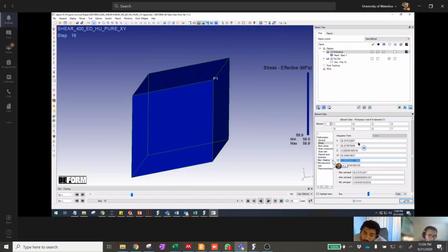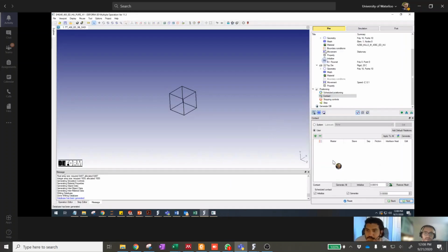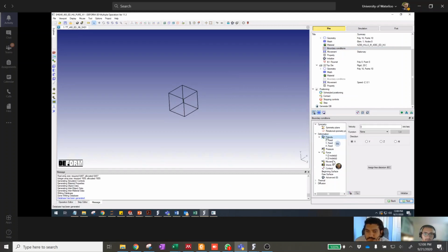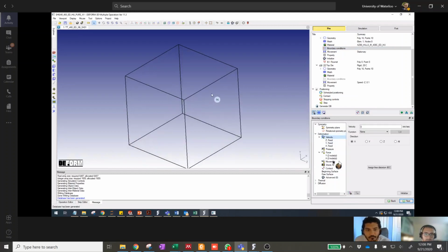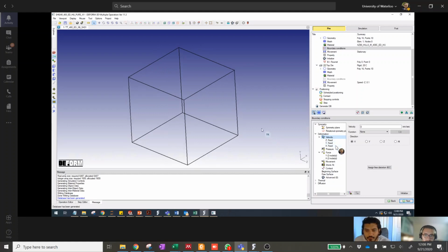Okay, do this. Go back to your boundary conditions. Okay, so this whole face is fine, leaving it fixed. This node down here, remove the constraints on that. Constraints on the Y, or both the Y and the Z?